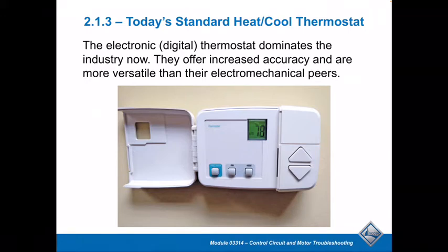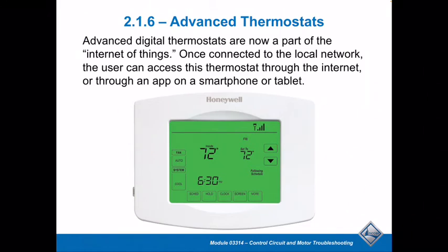You don't like it to be too close, otherwise you're going to get it switching modes from heating to cooling. So a dead band is important. Commercially, that's commonly done. So looking further, let's take a look at some of the more advanced thermostats.